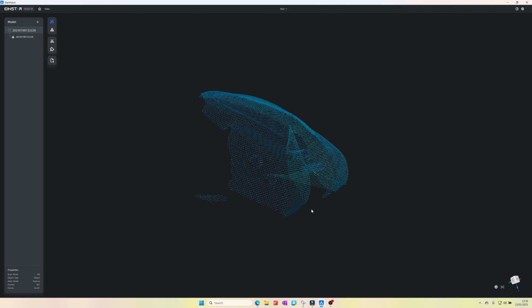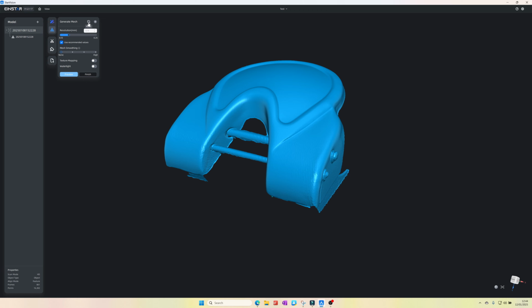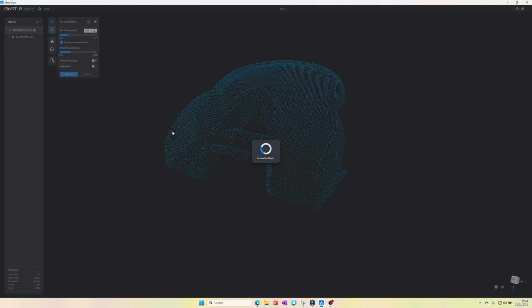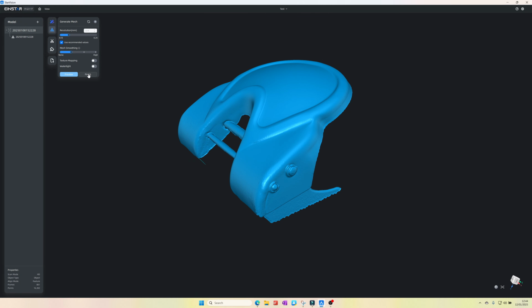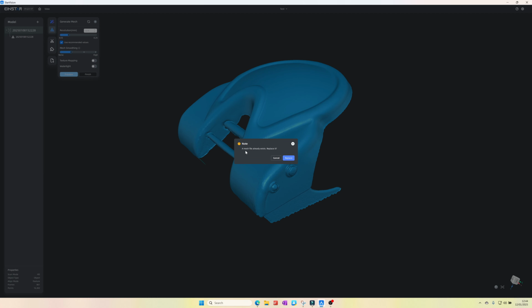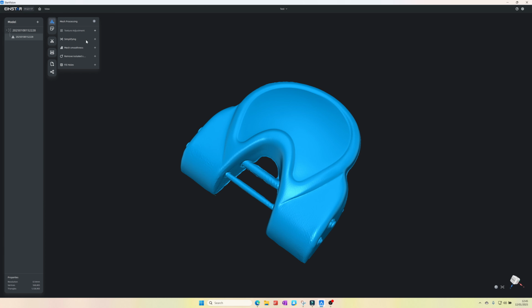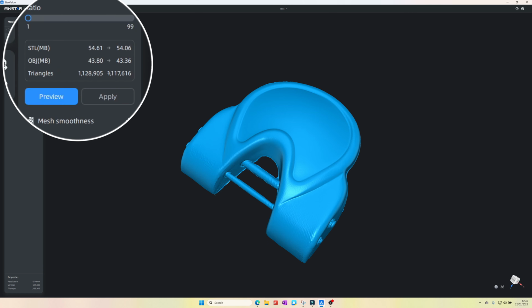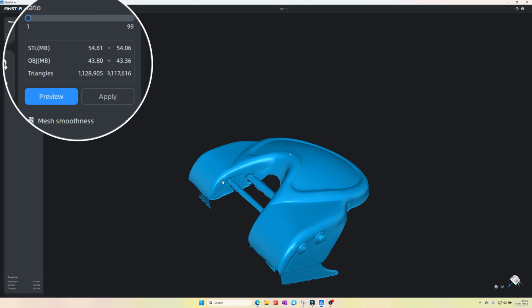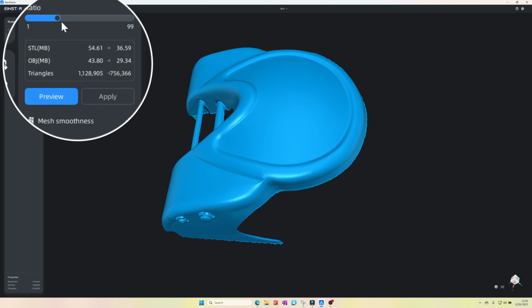With smoothing disabled, noticeable surface roughness and the orange peel effect are evident. Adjusting the parameters requires clicking Reset. Let's reapply smoothing with the same resolution, and the result is visibly improved. Once the mesh is complete, you can simplify it. For instance, a model with approximately 1.1 million triangles can be reduced by 50% without losing significant detail, making it easier to manipulate.